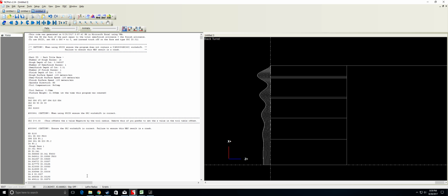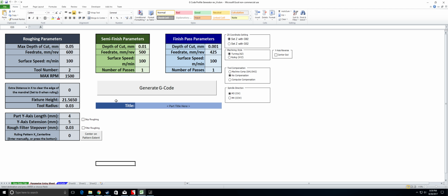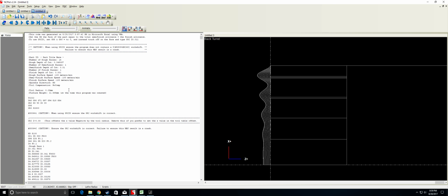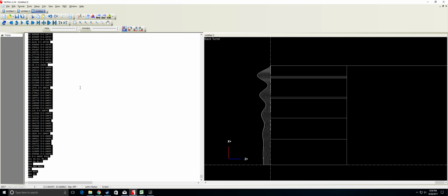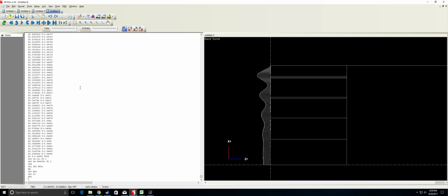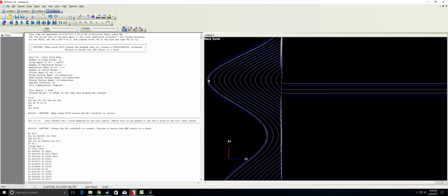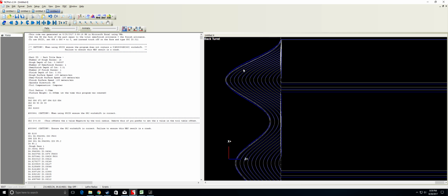Okay, so go ahead and save this as a reference. Back here on this sheet, filtering is not really for the 2-axis turning, it's for the 3-axis. So come over here to compensation. Now you see this said no comp. Okay, and now I went ahead and put this in here, and you can see the toolpath is compensated